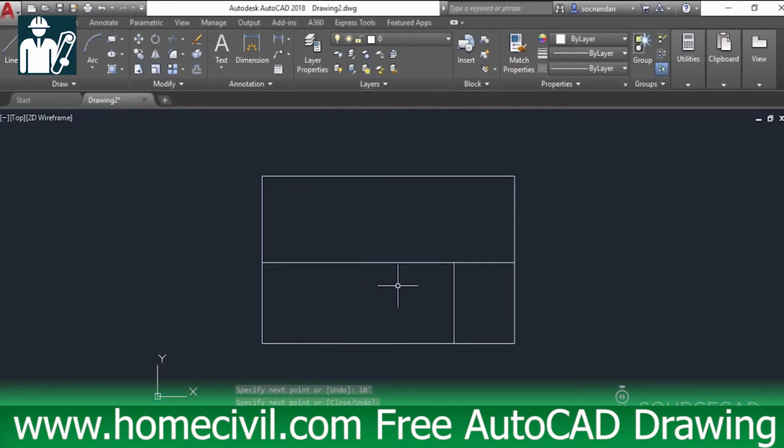All right, so here we have it. Now go to the line tool again and go to this end point and join it with this intersection point. Press enter again, select the next end point, join it here. Now the boundaries of this floor plan is complete. We need to add thickness to the wall.